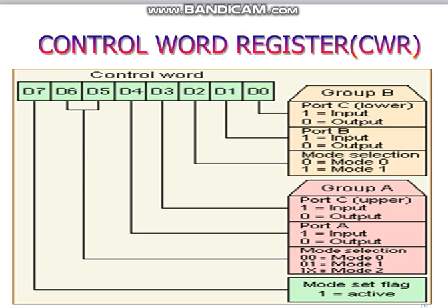You know that when A1 and A0 are operated at 1 1, you will have the control logic. Your control register will be selected. So this is my control word register, which says what each and every port is going to do. This control word register consists of a total of 8 bits, D0 to D7.